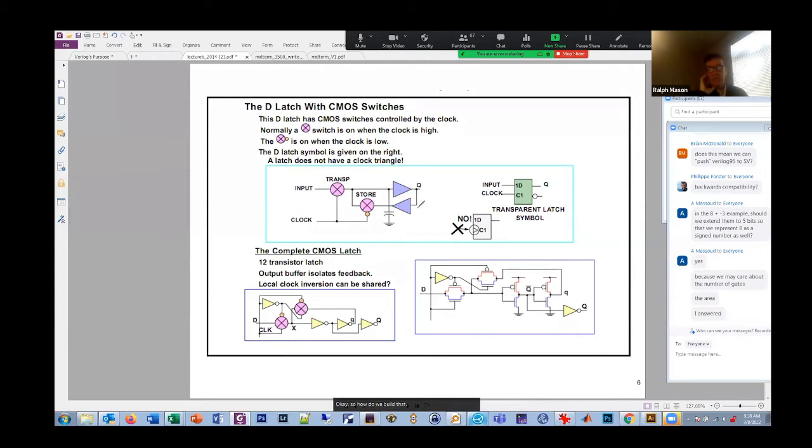Well, there's some different ways to do it. One way is those two pole switch, we can do that with two transmission gates. So the two transmission gates, we clock them the opposite way. One is active when clock is high, the other one active as clock is low. So when clock is high, the signal passes through. And when clock is low, the signal loops around. Okay, so the two pole single throw switch can be built with two transmission gates.